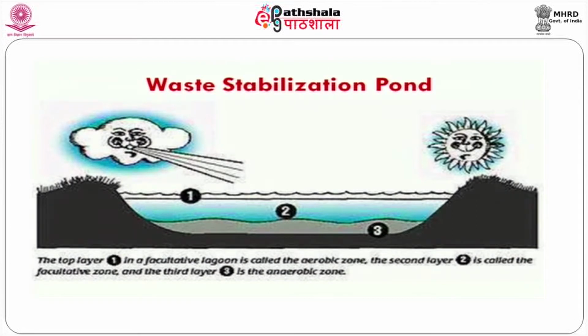Oxygen liberated by photosynthetic action is high when compared to oxygen that is naturally transported into the bulk phase by natural transfer mechanism. The middle layer is the facultative layer. Facultative bacteria can survive in the presence or absence of oxygen. Even if oxygen is there, they can tolerate it.